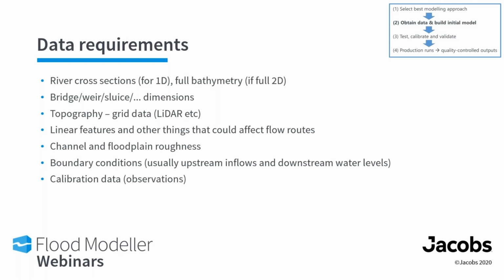Boundary conditions are the things that drive how much flow goes into the system and define the downstream boundary, which could be a water level or a rating curve, which is a relationship between flows and levels.